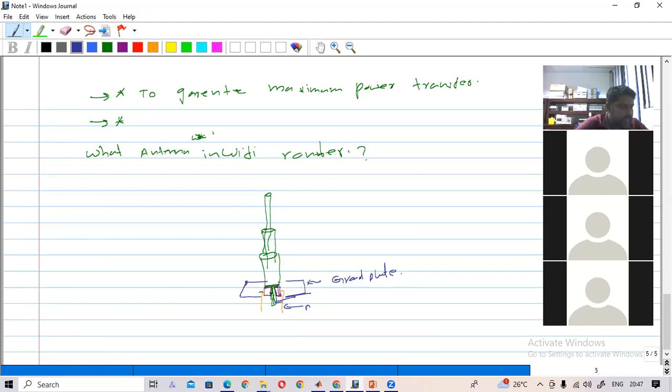So this kind of antenna is a monopole antenna, and the length should normally be lambda by 4. It is a quarter wave monopole antenna. The antenna length will be lambda by 4, where lambda is the design frequency wavelength. And in Wi-Fi routers, we have monopole antennas.